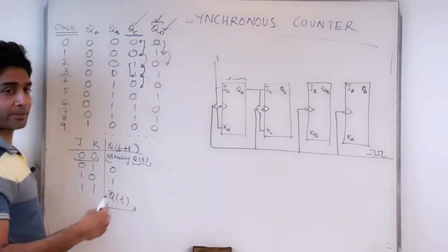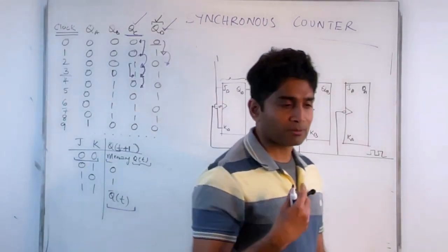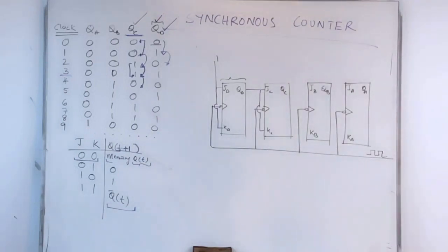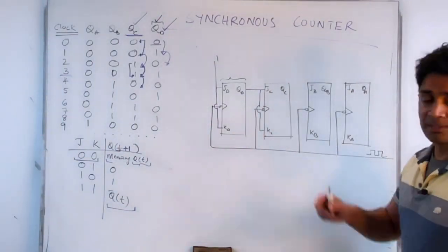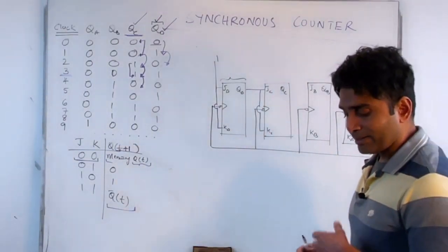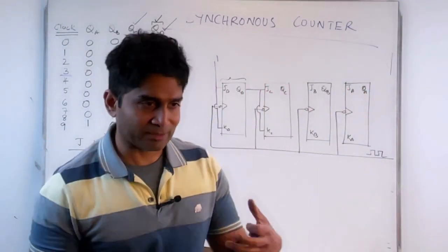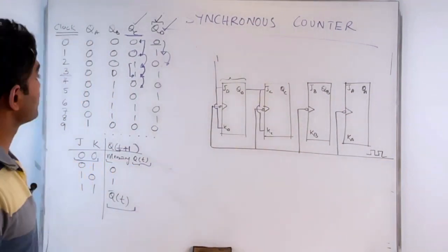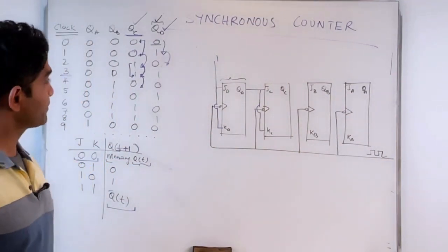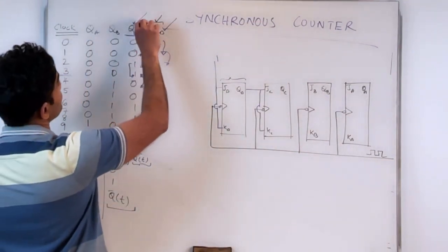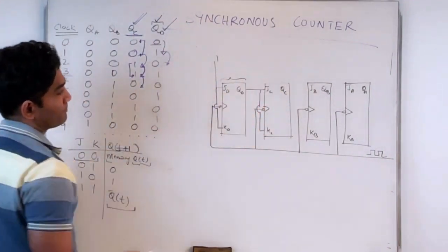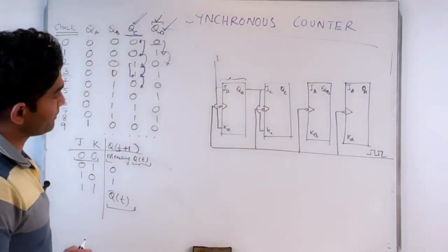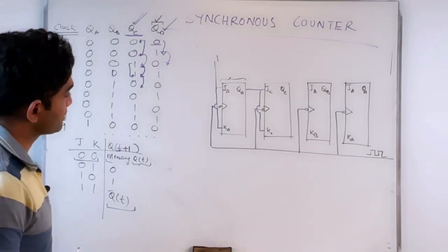And so on, the behavior continues, right? So in one clock pulse, I'm configuring this flip-flop in the memory state. And in the next clock pulse, I'm configuring this as a toggle state. So it's kind of oscillating between those two stages. So that's good. So that works. So now I obtained QC by this modification or by this configuration.